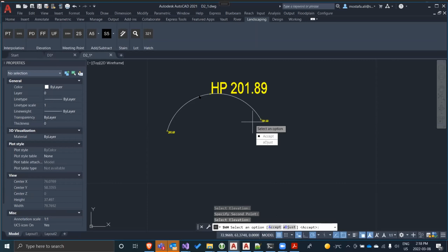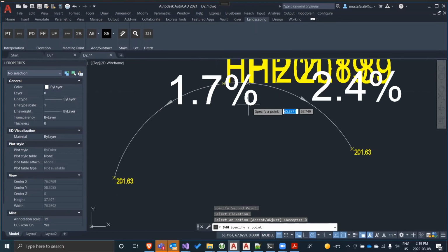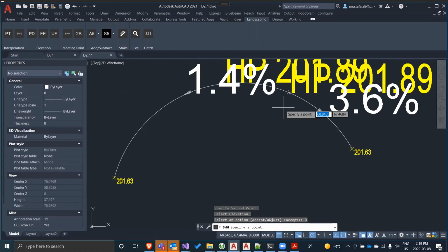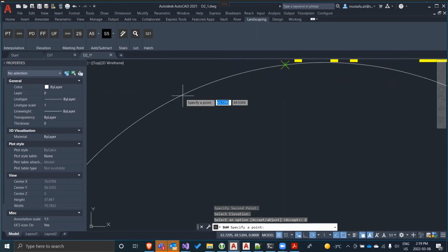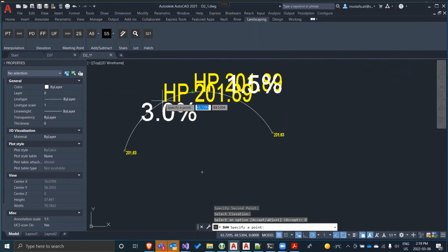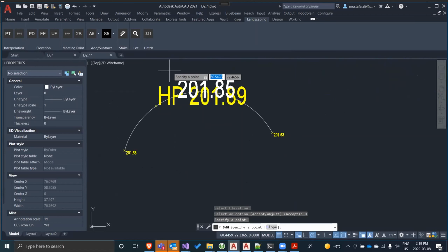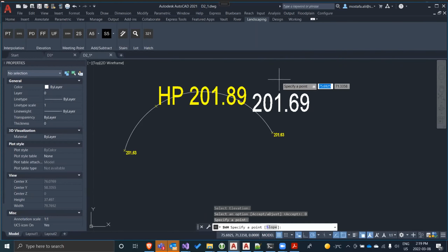In this case, you'd rather change the slopes you started from, like you started from 2% and 2% from here. Now, if I click adjust, as I move here, I see that if I am here, this will be 1.4 from this side and 3.6 from the other side, or it will be 2.7. So again, I can move along the curve and find the point I would like to use, and this will give me the point based on slopes that are now different from before.